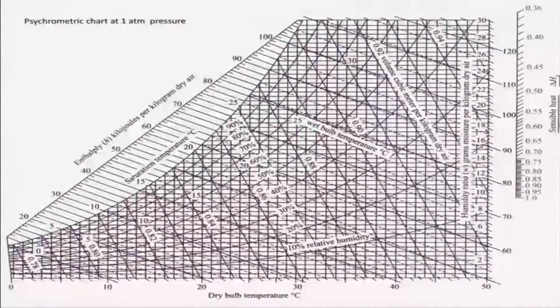As I was saying, the line that was earlier green is the specific volume per kg of dry air, the water vapor volume per dry air. And the dashed lines are the wet bulb temperatures, like in this case 25, in this case 30, and then it goes 20 and like that, 15, 10, 5, 0.